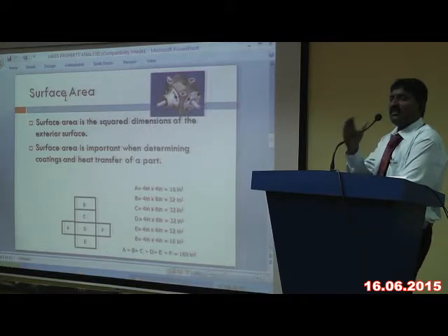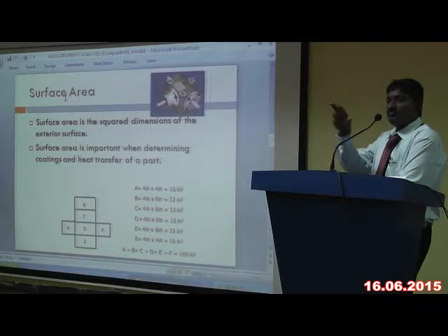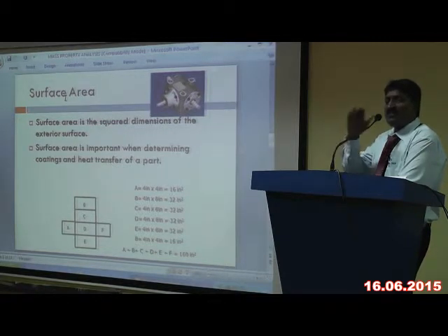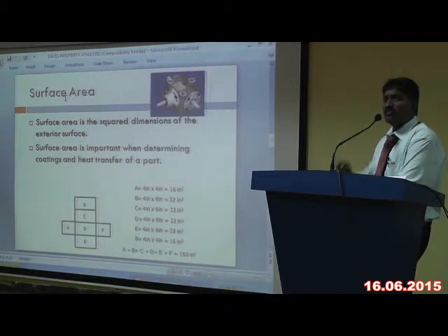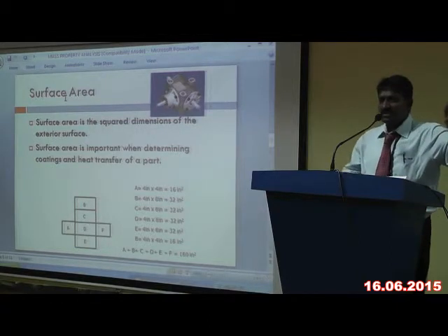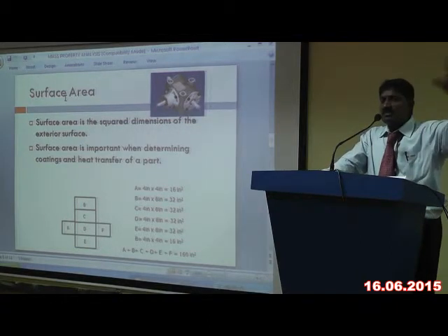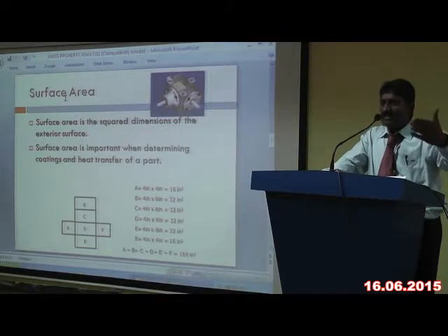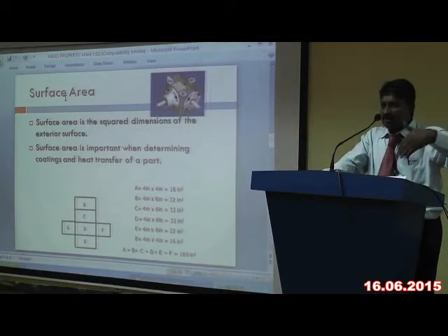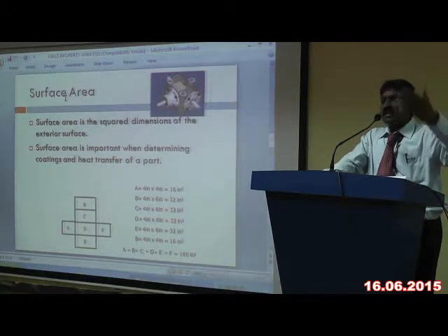Now we want everything to be manufactured so that the moment it comes out of the mold, the plastic injection molding machine, it is shiny. It gives a glossy surface. The surface is clear. There is no additional work in that. I don't have to spend too much money on surface finish. Whereas if I take a cast iron piece or some other piece, I have to go for additional operations, and I have to complete it, paint it, do the spray painting or corrosion resistance painting. So all these 4 or 5 operations are extra.